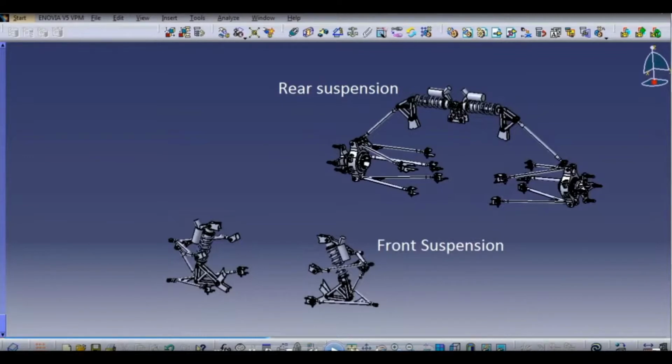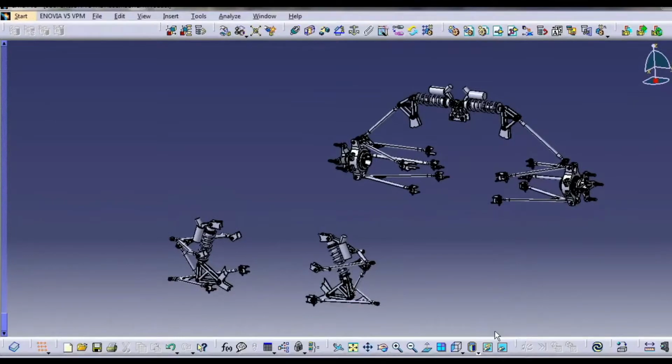Now, for designing a suspension system of a vehicle, first we have to start with the calculation of the CG height, because every point and parameter of a vehicle is related to the CG height. To do so, get the idea or reference of the previous year vehicle CG height by keeping the ground clearance as minimum as possible. Adjust the CG height. After that, consider the weight distribution on both sides, that is the front and the rear side. By keeping the weight distribution equal, we can achieve a neutral steer condition.